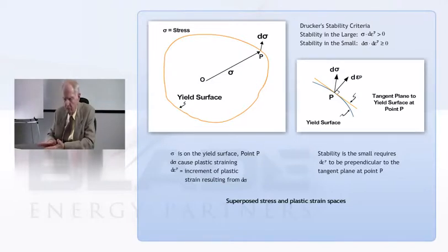And in particular with soils, you find that you'll be able to shear it, but the motion occurs over a single sort of a slip plane. And it's that sort of thing that you need to think of when you're trying to study something like a landslide. These materials have the characteristic that when they're in a compacted state and you shear them, the volume increases.